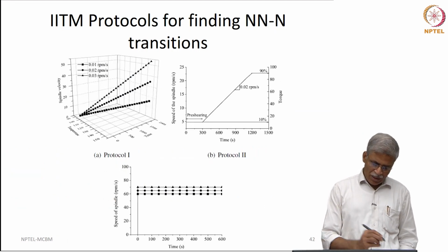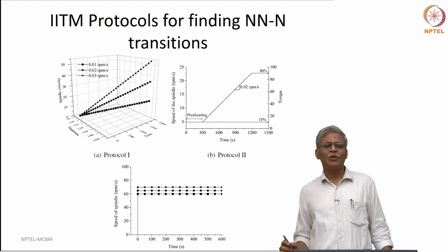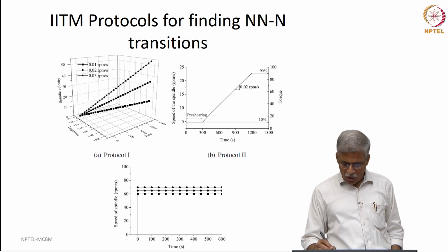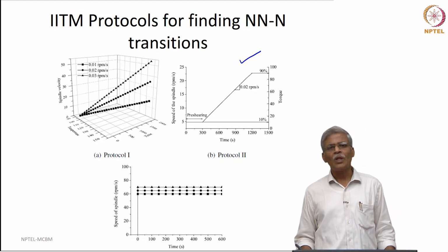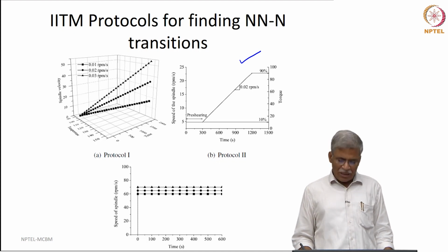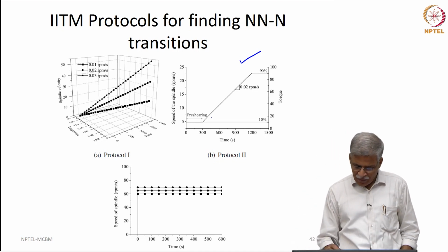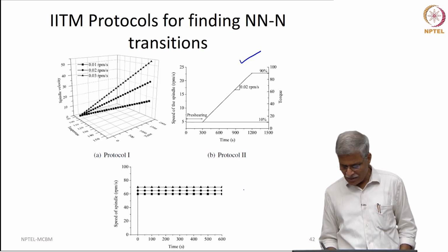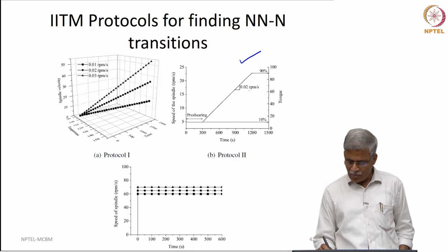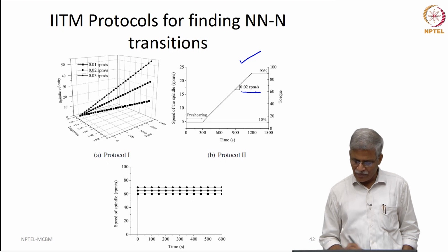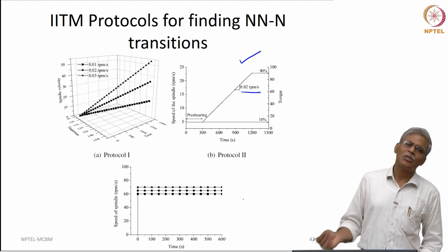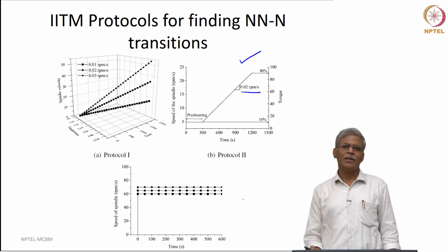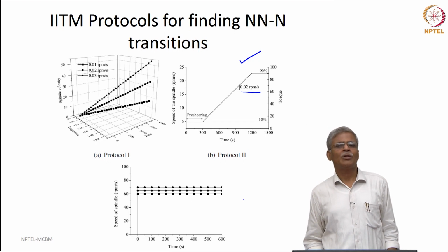Now, how did we actually do it? We came out with a completely different way of looking at this. For instance, most of the procedures here talk only in terms of this shear rate sweep. That means you do a pre-shearing for some time, and you can see in the y axis is the spindle and in the x axis is the time. So, you typically do a shear rate sweep with an increment as prescribed like this. If the response of the material is non-Newtonian, when you plot viscosity versus shear rate, you are going to get the appropriate data for use in a non-Newtonian fluid model.